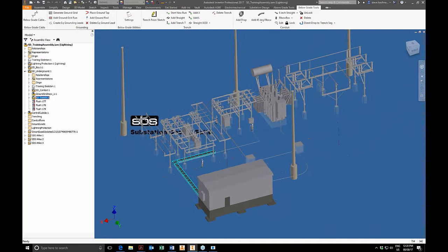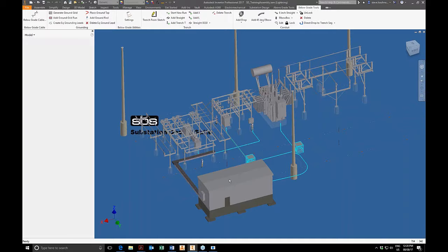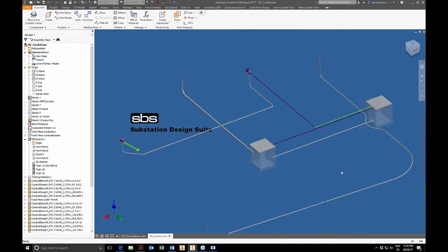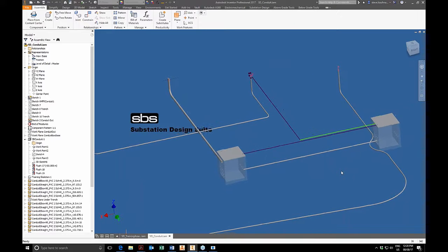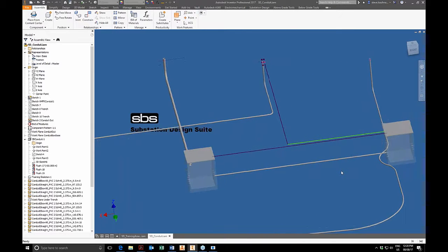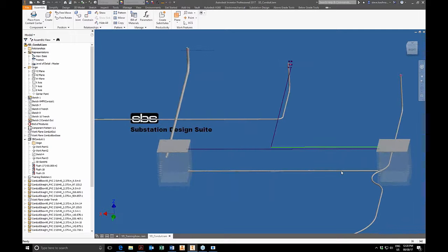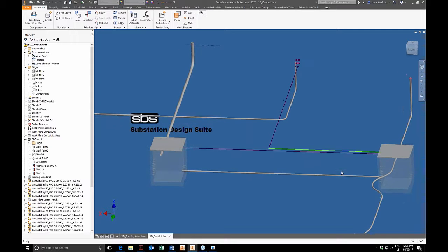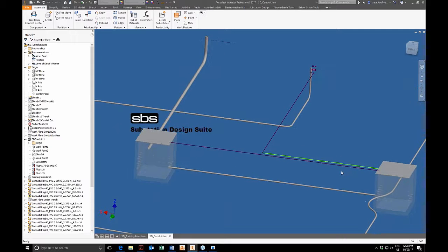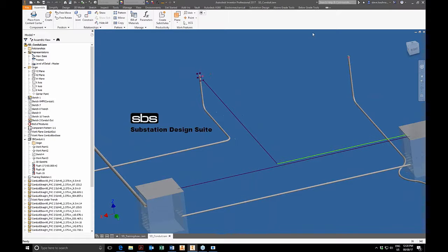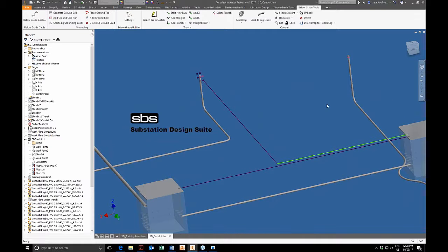If we wanted to place some conduit, let's open up the conduit. And again, I'm going fast. This is being recorded, and we'll take questions at the end here. So here's my conduit open here, and I have conduit sketches, much like the trench sketches. In typical Inventor method, you run items on a sketch. So I'm going to place a piece of conduit on here.